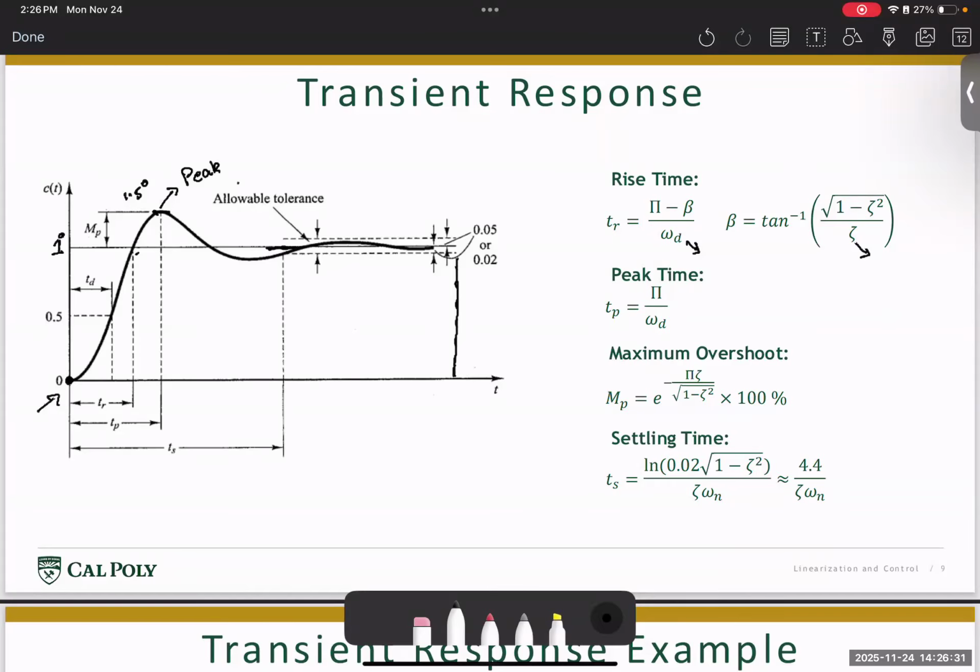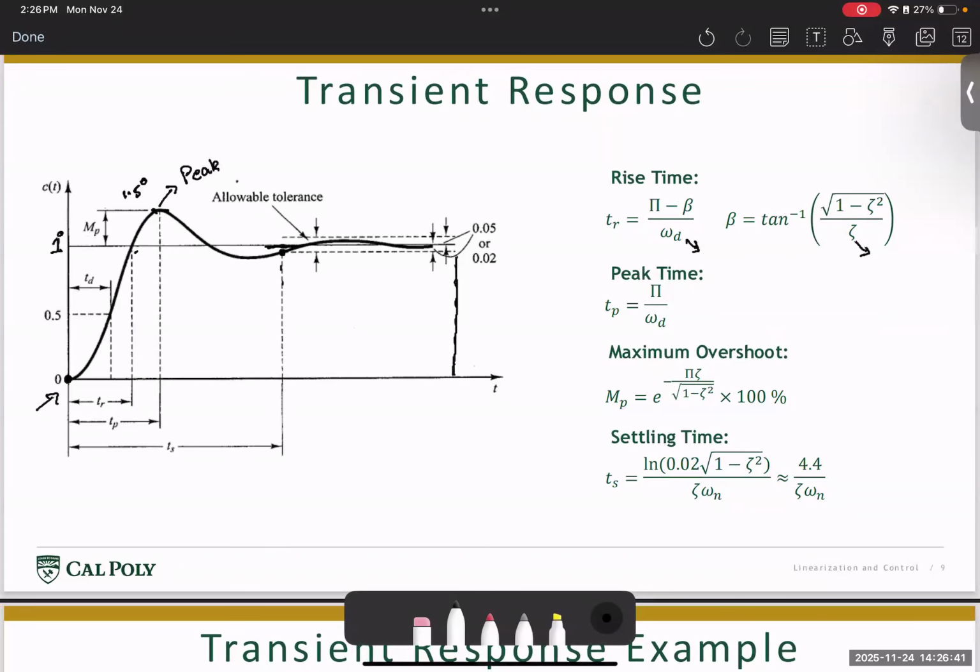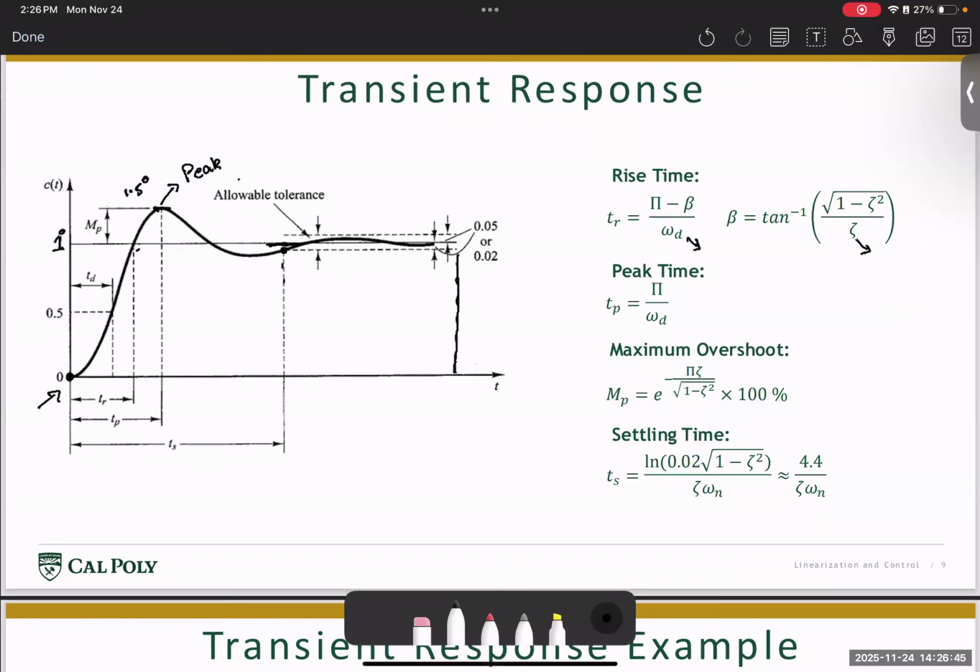So if you're reaching somewhere about 0.98 degrees of pitch, then the first instant where you reach 0.98 degrees and you start to settle there is called the settling time, which is given by TS, in the equation on the screen. It can also be simplified to about 4.4 divided by zeta omega n. And for a typical second order system, the settling time can be approximated as this.